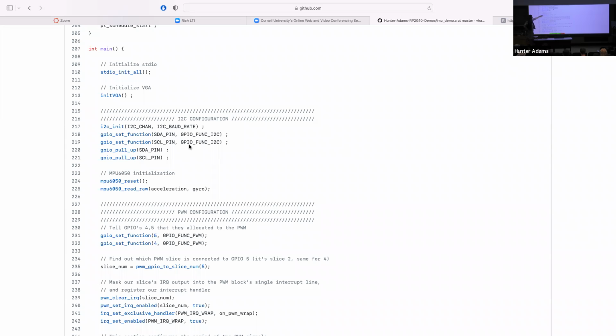This one here. Yeah, it just stuck there, and we later found out that until we reset the MPU as well by cutting off the high voltage and then reconnecting it, and then resetting the RP2040, it will work this way. Like you have to reset both of them. Okay. And you have to reset the MPU 6050 first. Okay, that is good to know.